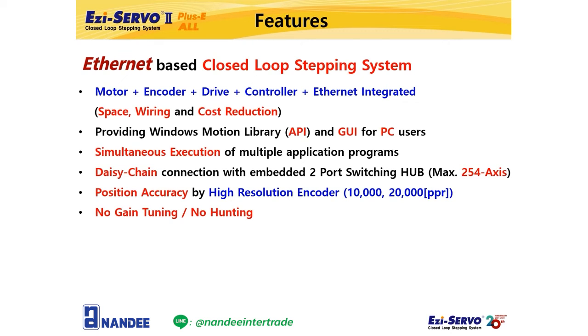In general, when controlling a stepping motor, motor heat is a problem because the maximum current flows regardless of the load, but since Easy Servo controls the current according to the load like a servo, it can relatively suppress heat generation compared to the conventional stepping motors. We have looked at the features of Easy Servo 2 plus E-All until now.